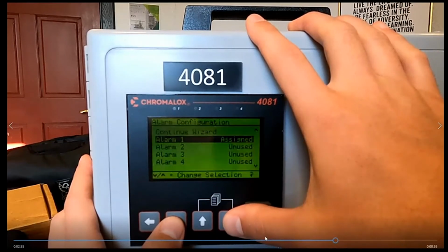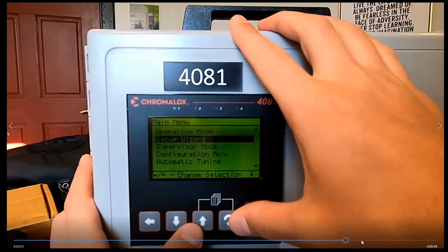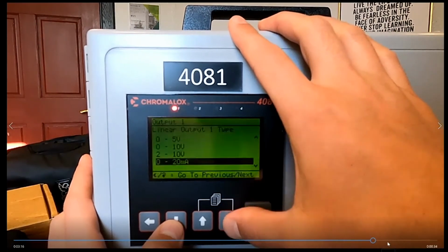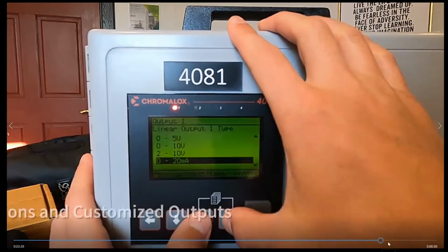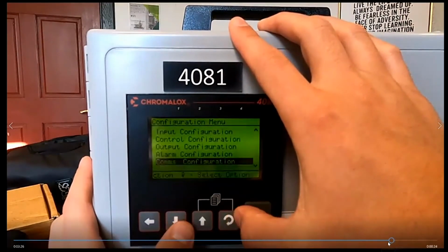This is power up, auto configuration. So a lot of the same stuff that Vince just touched on in a much shorter version. I'll skip ahead just a little bit, back to configuration modes at 10. You can have up to three outputs, I think you saw there. Here's where you're selecting the type of output, back to analog. And again, you still have to scale it and calibrate it.